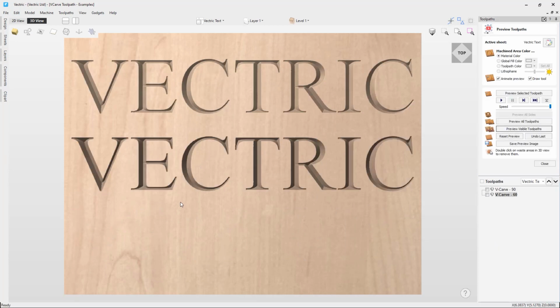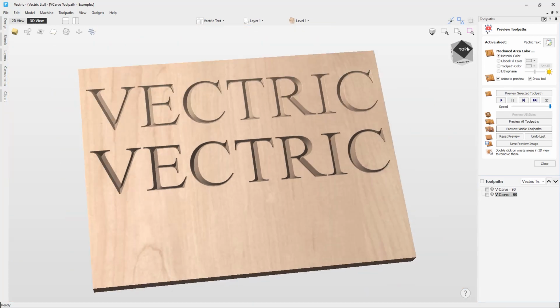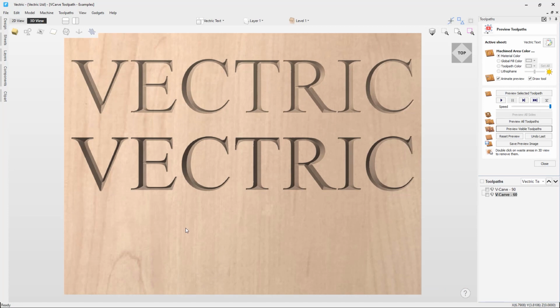And you'll see there's quite a difference between these two different toolpaths. This one is cutting much deeper because of course the angle is much smaller, so we can put that tool even deeper into your material to give you a much deeper cut if you would like. So I really suggest that you go ahead and play around with the different tools that you have on hand to see your best cuts. Okay, we're going to go ahead now and close this down.